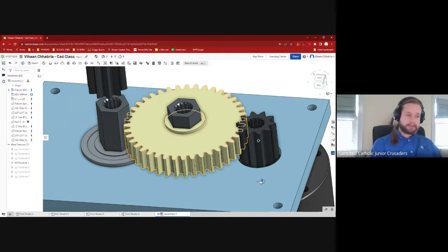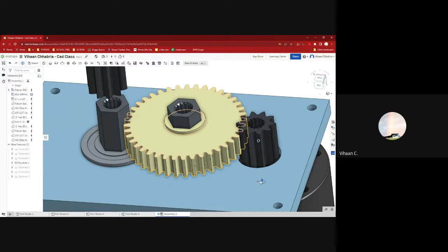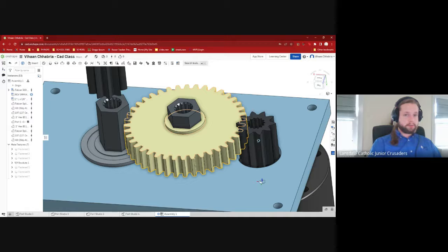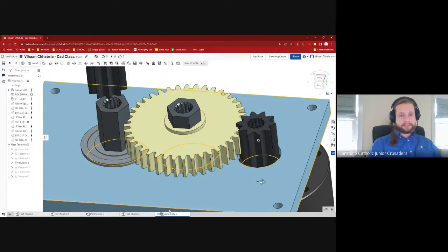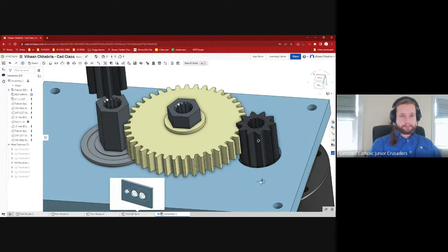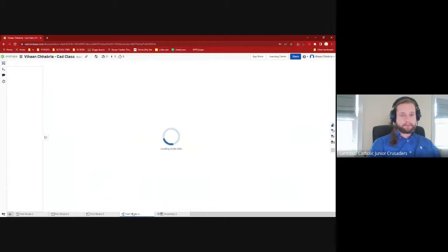Well, I would recommend, I think 12 tooth comes in half-inch hex, maybe. Possibly. I'm not entirely sure. So would I still use a 20 tooth gear? You may need to use a larger gear. Why don't you change the center spacing on that second gear train so that it ends up with a 12 tooth to a 22 tooth and see if that's far enough apart.